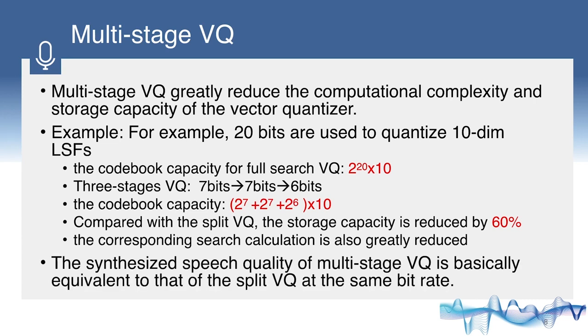The synthesized speech quality of multi-stage VQ is basically equivalent to that of the split VQ at the same bit rate. The multi-stage vector quantization system has made considerable improvements in terms of reducing the amount of search calculations and reducing the amount of codebook storage.